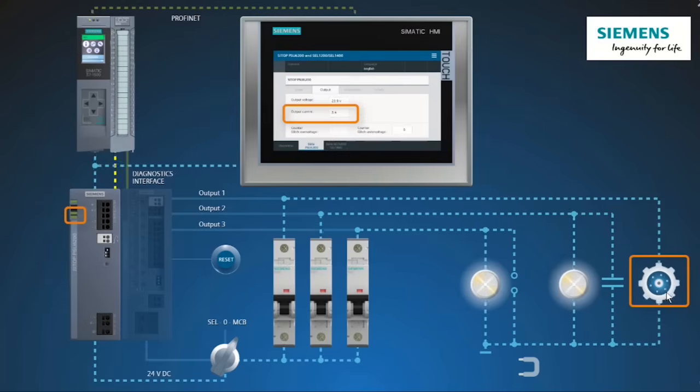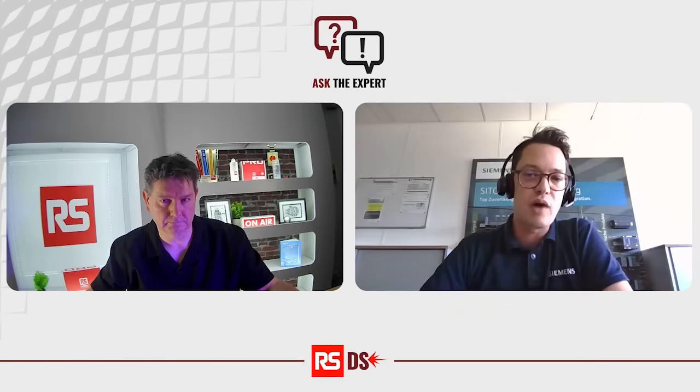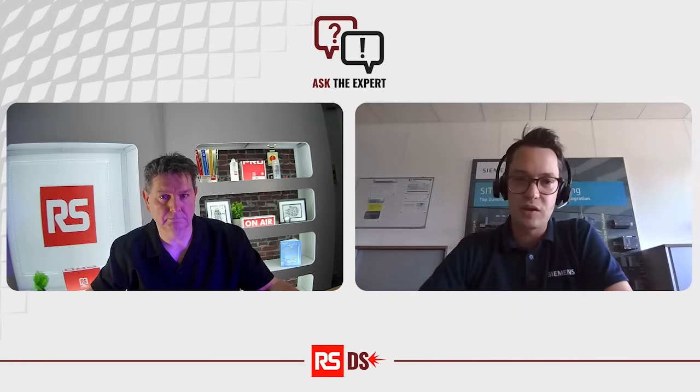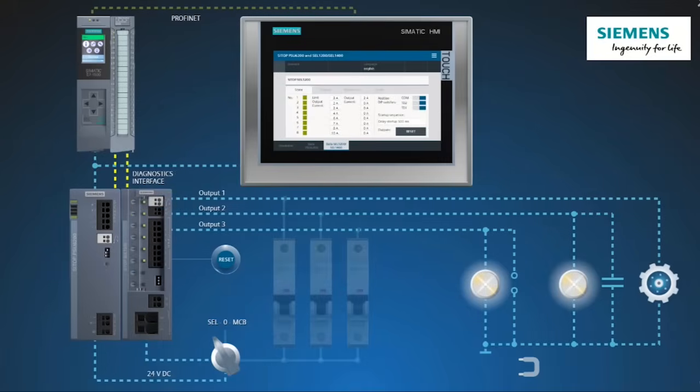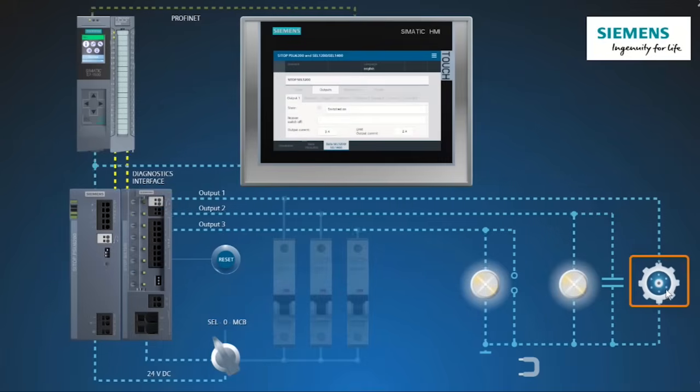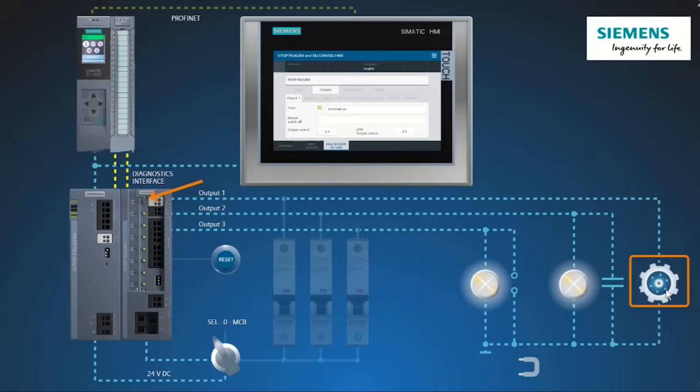And you see also on the left side there is this little utilization monitor where the second LED goes on. Yeah, and now here is the big thing. We do not have enough short circuit current that the MCB will trip. And in that case, it could lead to a failure, or it could lead that the wire will maybe be damaged. And now I switch to our selectivity module, so now the selectivity module is on,